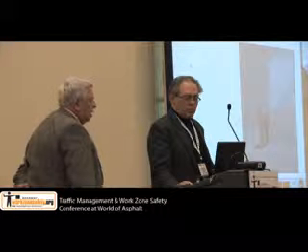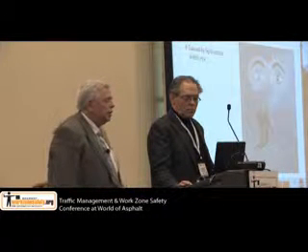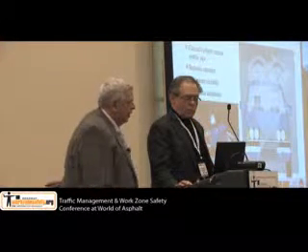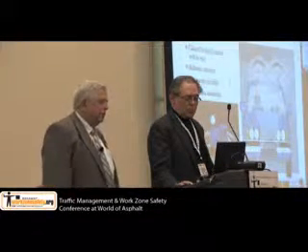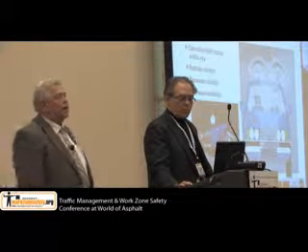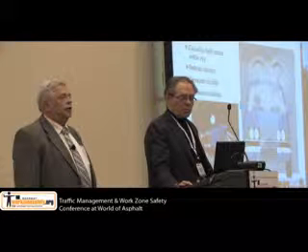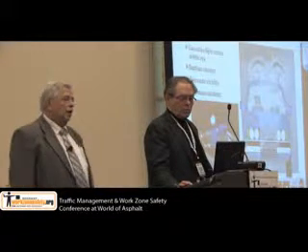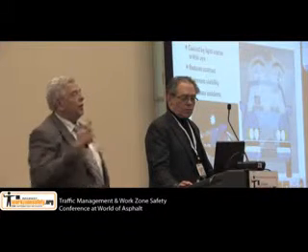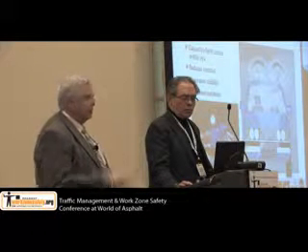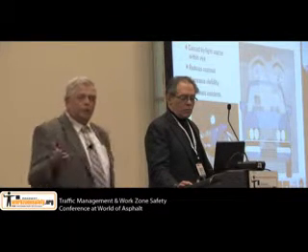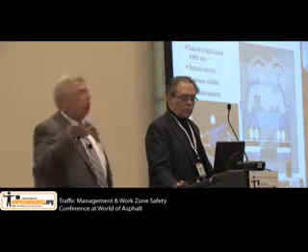Glare is a hard one. It's a hazard for everyone. It reduces the visibility, it reduces the contrast, it causes a lot of accidents, and again, it's a question of placement and movement. You have to place the lighting so that you're eliminating glare from where you're working, and you have to make sure that if you move your work that you adjust the lights to make sure that you haven't moved into the glare or the shadows.